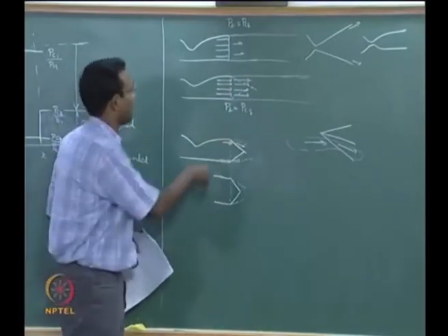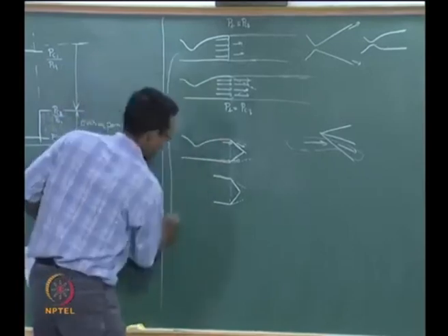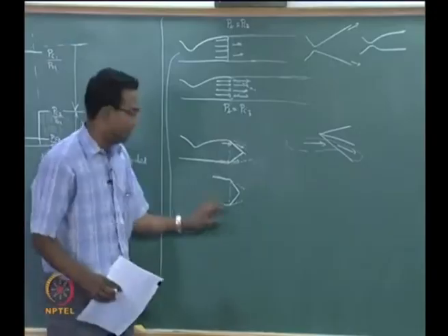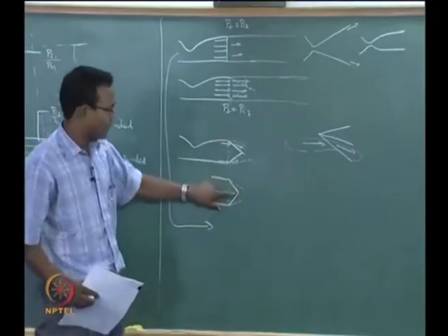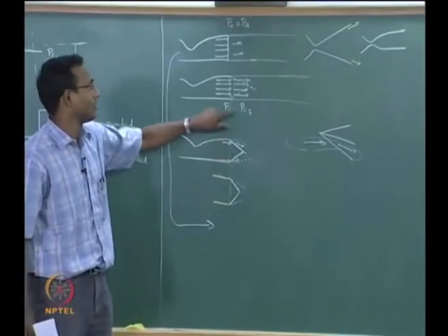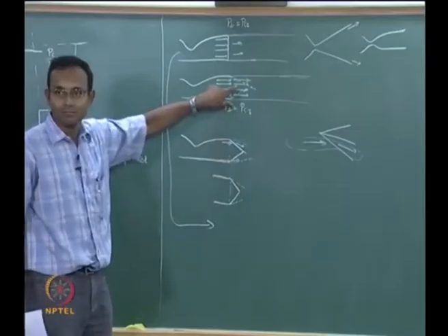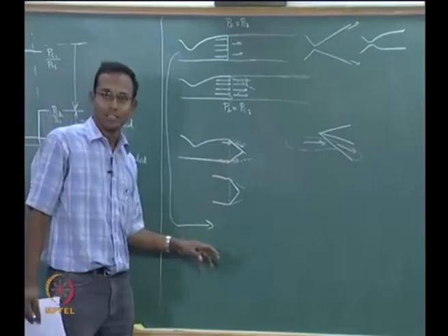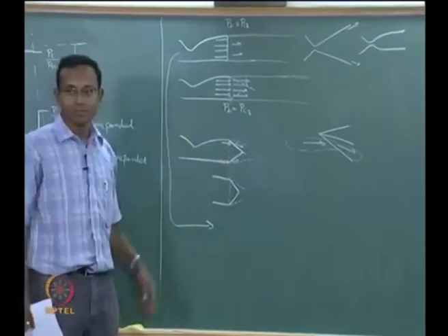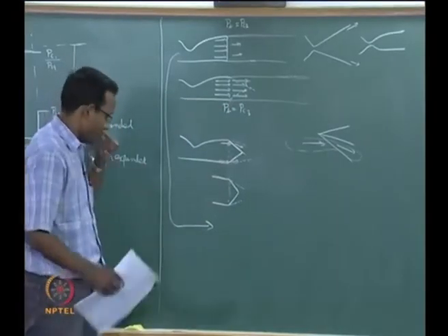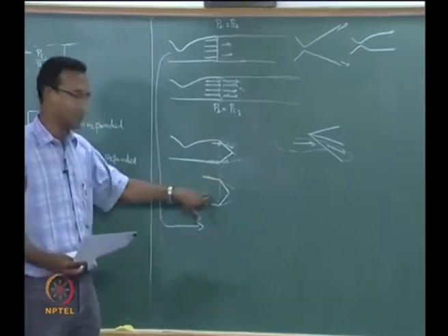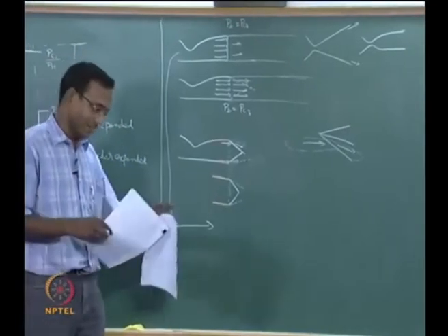Okay. Of course, I have not drawn it the correct way, this picture should have been in here. That is the full normal shock, it becomes a high angle oblique shock, then a lower angle oblique shock, eventually becoming the Mach angle. This is the whole thing that is going to happen as I decrease my back pressure, it is going to tend to this finally. We will talk a little more about this between this last picture and this picture after some time. Okay.